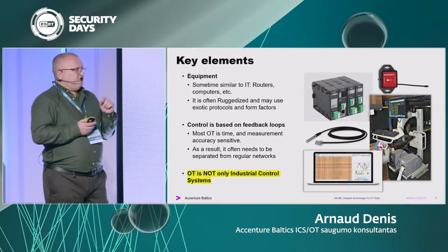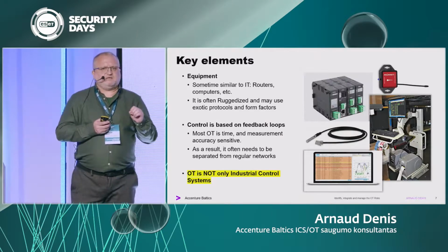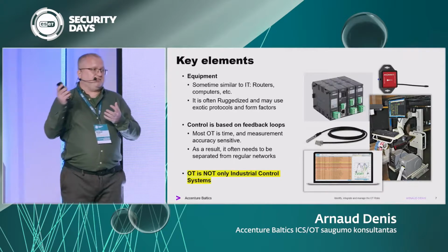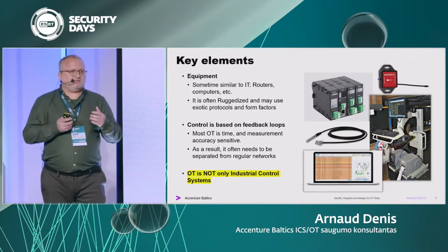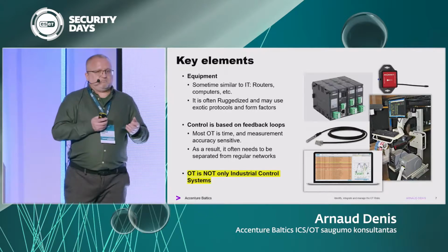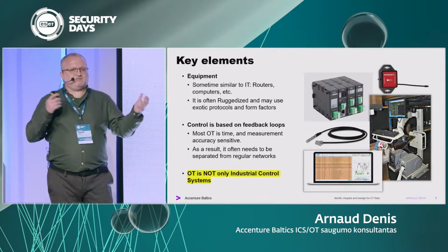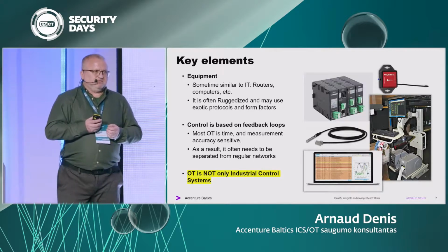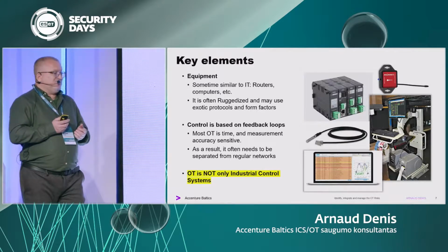It's also usually very time sensitive. OT is designed to react to things happening, things it's monitoring. So if you don't pay attention to the timing, that's a problem. If you start scanning while it's trying to do something, you might slow it down and cause problems. That's why you need to be careful about what you do with it.